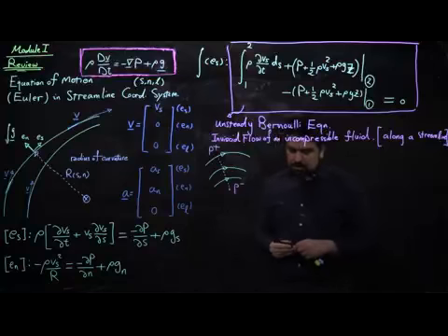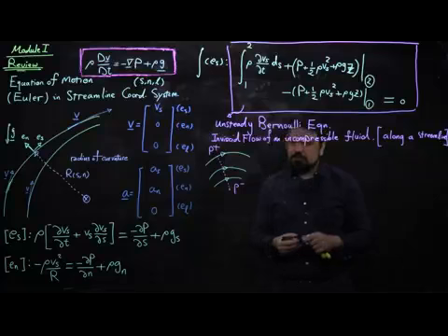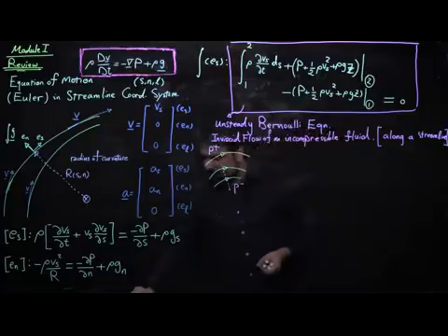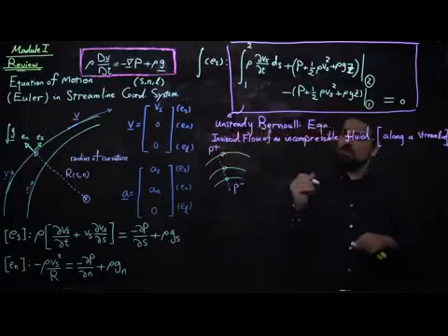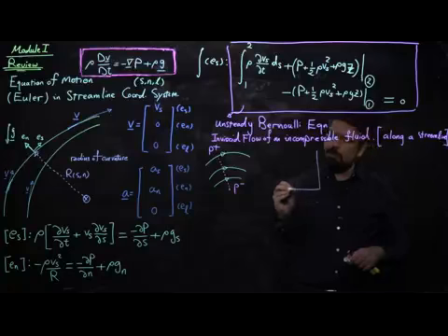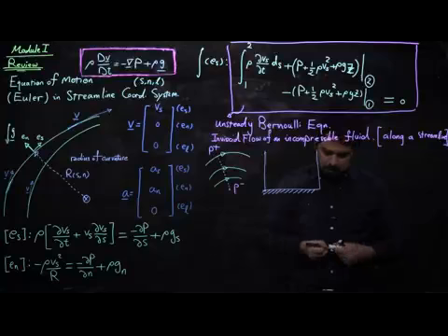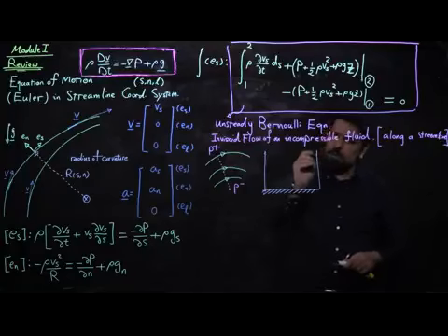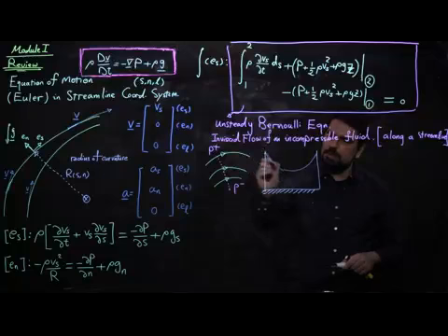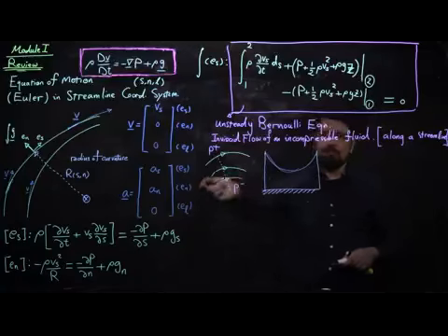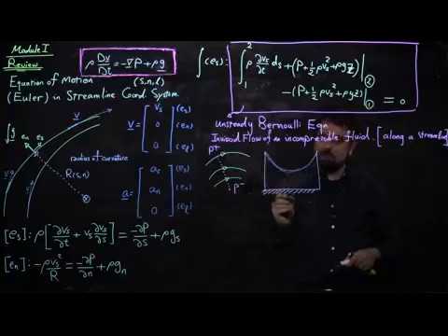We saw the consequence of this in many different applications. For example, going back to the example of rigid body rotation, indeed we saw that if we have a tank that is going through rigid body rotation, one way of thinking about why we get a parabolic profile is the fact that if you look from the top, all the streamlines are curved because everything is rotating here.